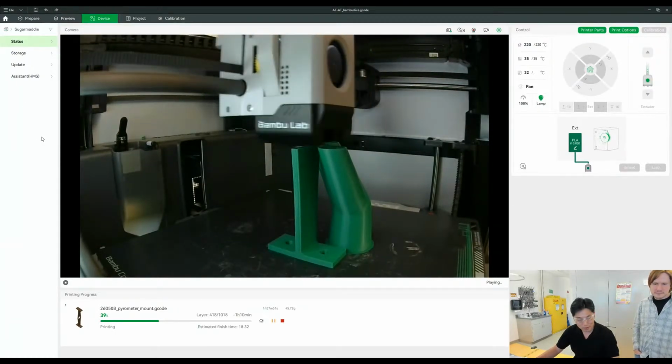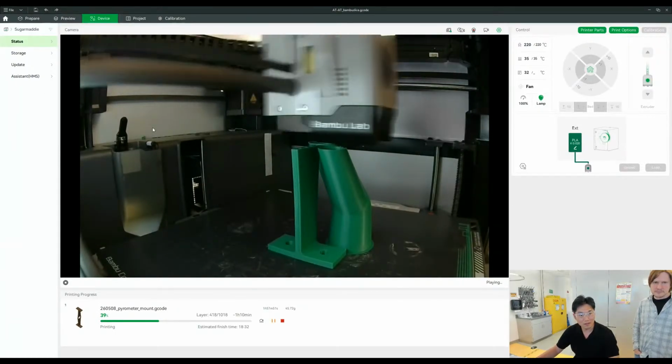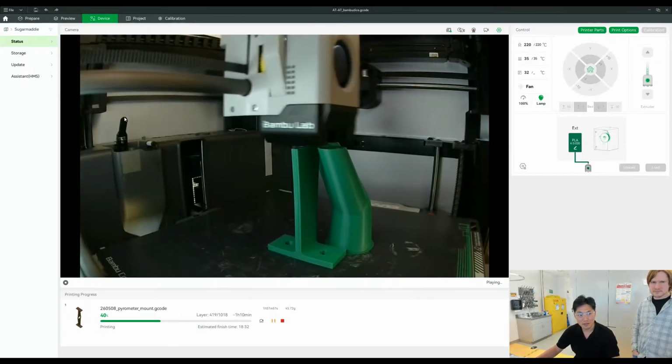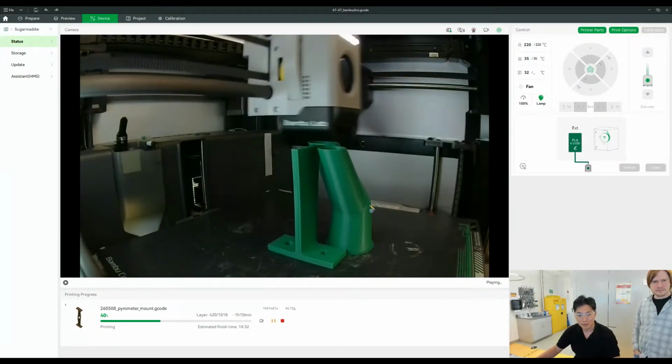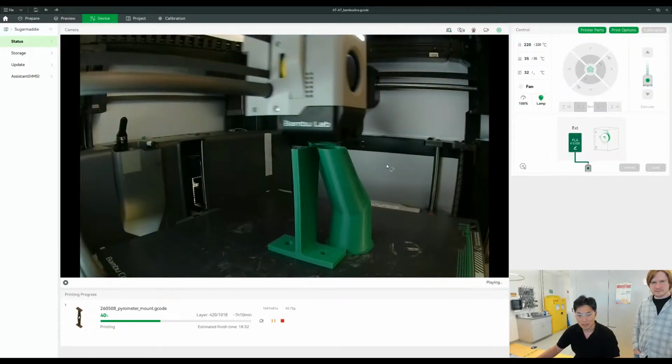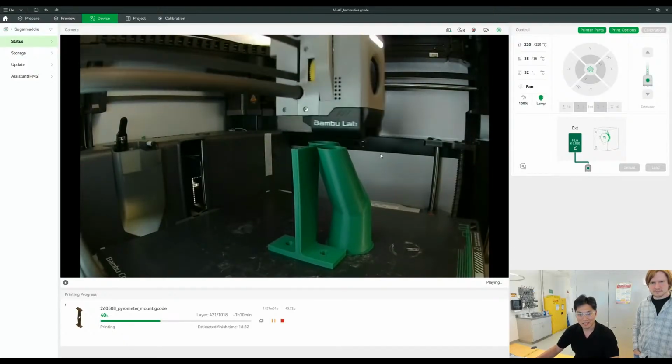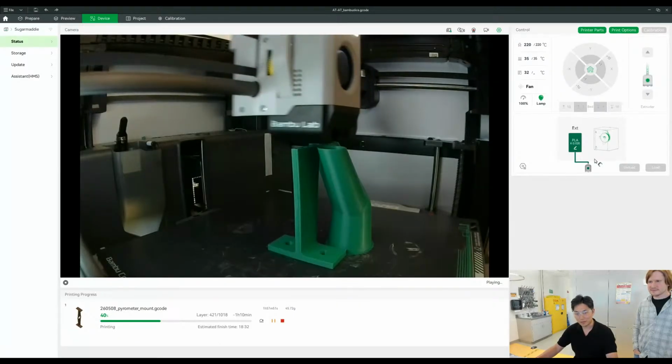This right button is the dimensioning button. So if I put another sketch on this, just make a circle, tap the right button and I can dimension right away. That was pretty good.